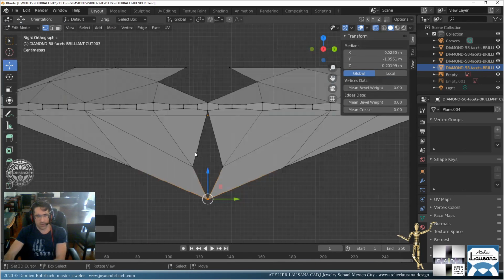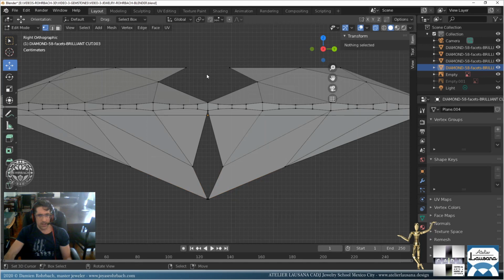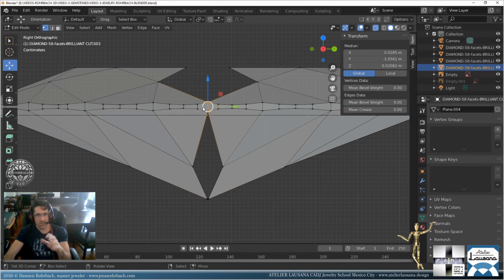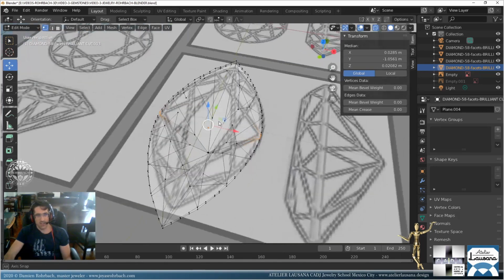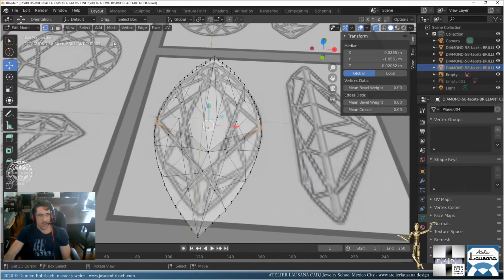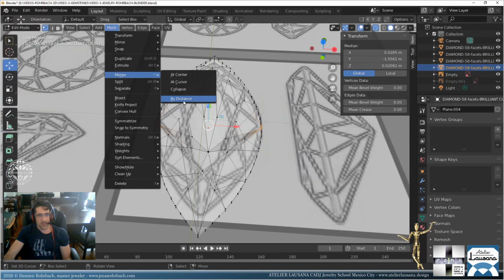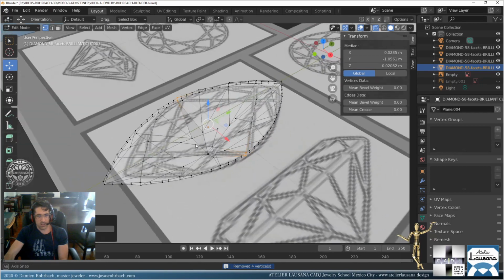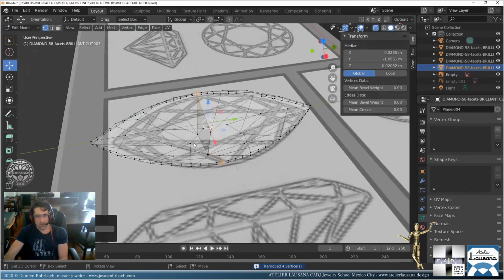Okay, let's go to the side view. 3. Alt A, B. So like always, check that you have the transparency activated so you get the selection on all the sides. Let's make mesh merge by distance. Okay, they were merged. So we should be good.